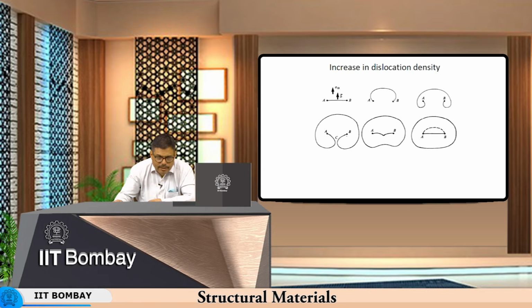Now what happens is, as these 2 points come closer and closer together, the dislocation tends to get annihilated, in the sense that these will be of opposite signs, and therefore these 2 points get joined together. So you retrieve the original dislocation and have another dislocation which was created as a result of the stress acting on this dislocation. So now you have again this dislocation ready to multiply. So now both these dislocations are going to multiply.